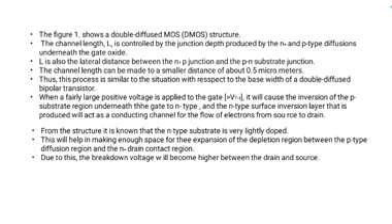Here you can see the channel length L. The channel length is a small distance, and when you apply the voltage, it causes inversion in the substrate, and the entire region forms an inversion layer, which acts as a conducting channel that allows current to flow from the source to the drain.